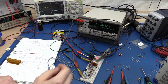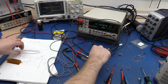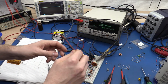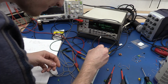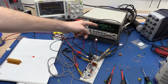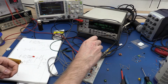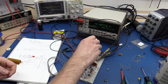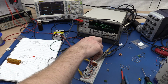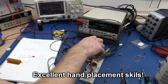It also shouldn't matter what the load is. Right now we have a drop of 1.8 volts, but if we have a larger drop of maybe more than 3 volts with this 1 watt LED, oops, you can see we get exactly the same current, and we can still adjust the current with the potentiometer. We can go way down. We can also go higher.